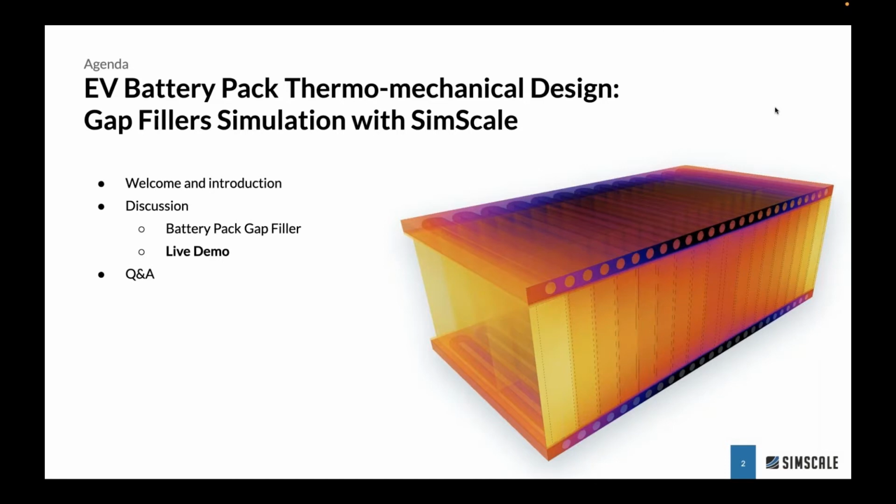In general, gap fillers can outperform thermal pads in battery pack applications to achieve lower thermal impedance, as the gap fillers basically conform to surface roughness before curing. And more importantly, different materials result in different mechanical performance, which we can post-process in form of, for example, the casing stresses of pouch cell swelling, but also performance differences due to drastic temperature gradients inside of the cells. My colleague David will later on show you how this will look in terms of post-processing.